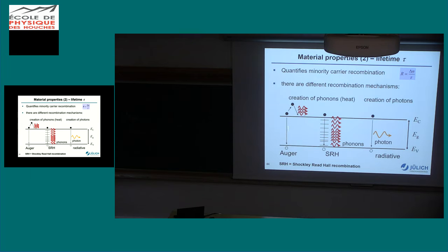Auger recombination is, the question is always how this electron-hole pair that we have at the beginning gets rid of the energy, because in every fundamental process energy conservation holds. You cannot just go down without dissipating energy, and on that scale this electron needs to know where it can get rid of this energy. Here it's easy. I can just give the energy back to the photon, and the photon goes away, and the electron-hole pair is gone.